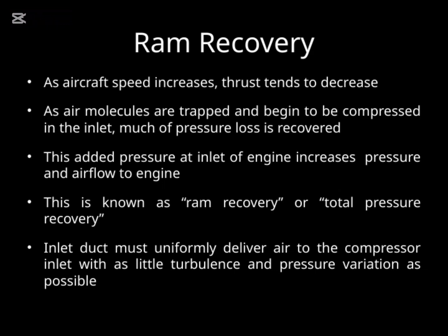But it's not just about increasing pressure. It's also about ensuring that the inlet duct delivers this air smoothly to the compressor. The duct needs to do this uniformly, with minimal turbulence or pressure fluctuations, because any disturbances can affect engine efficiency and stability. So, maintaining a well-designed inlet duct that provides a steady, turbulence-free airflow is essential to harness the full